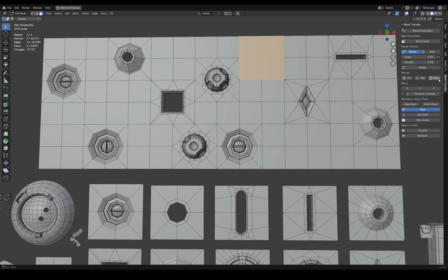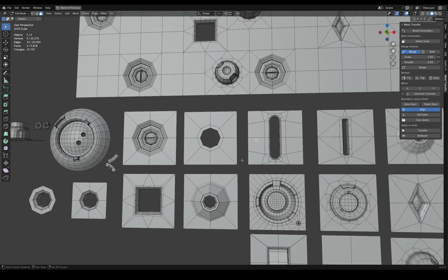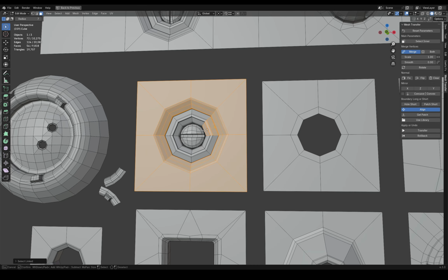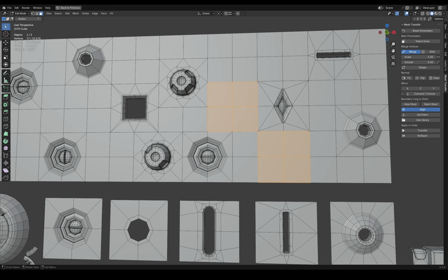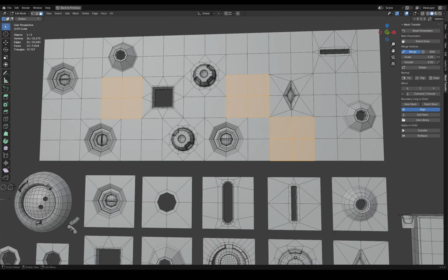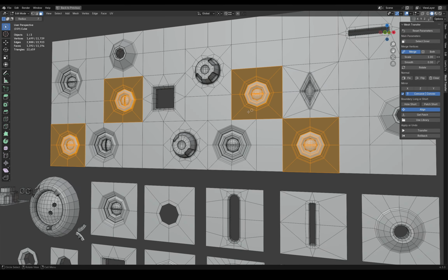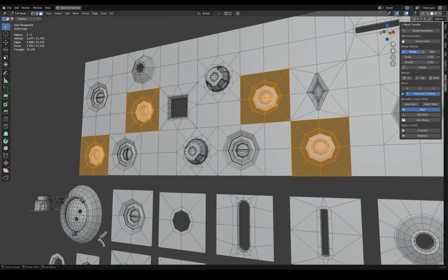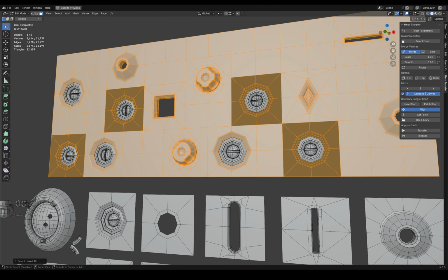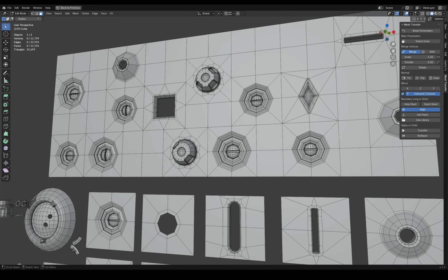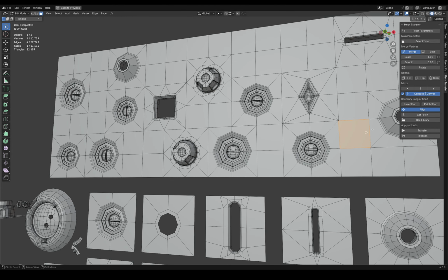You also have the ability to edit the normals of the polygons. This can help you correct the direction of the polygons if the insertion happened with the normals turned in the wrong direction. Also, if two regions have one common vertex, they are considered separate from each other, so you can use this. This can happen if your patch is made up of multiple separate meshes, but if the mesh is solid, it should be fine. In either case, you can fix it using the Normal Fix tools. You can also invert the normals of the polygons and clean them up, if they are not displayed correctly in the viewport.